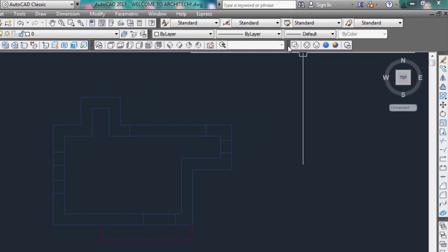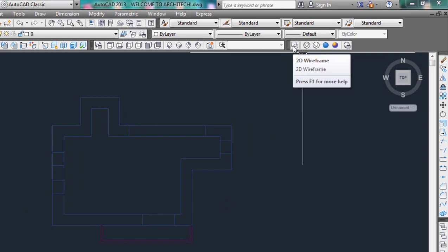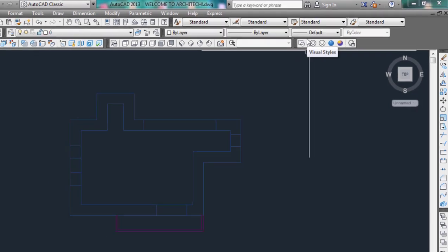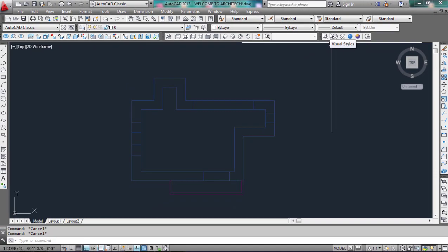So based on these view cube directions, you have 4 perspectives over here that can help you to see the 3D easier. Now moving on to the third tab, that is the visual style. All sorts of solid colors to your 3D object are provided through these tabs. Like if you want a visual style, you want actual color representation of your 3D project, you can observe over here.